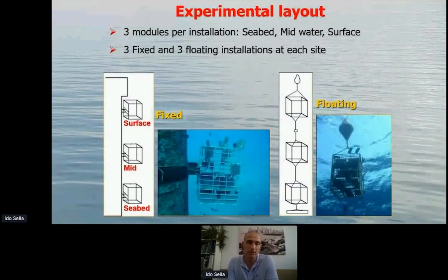It was a very simple experimental area. What we did is we used boxes with plates in them in different orientations, and I'm going to touch on it in a minute. The same boxes were fixed onto an oil jetty at a depth of between 27 to 30 meters. And nearby, the same area was floating on a buoy, anchored to the bottom. There was evaluation at different depths of the hydrodynamic forces and also the biology that developed, and also, of course, comparing between the fixed and floating structures.